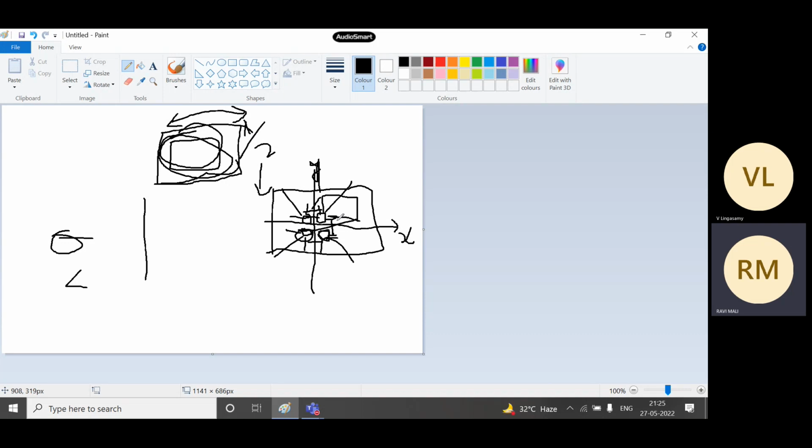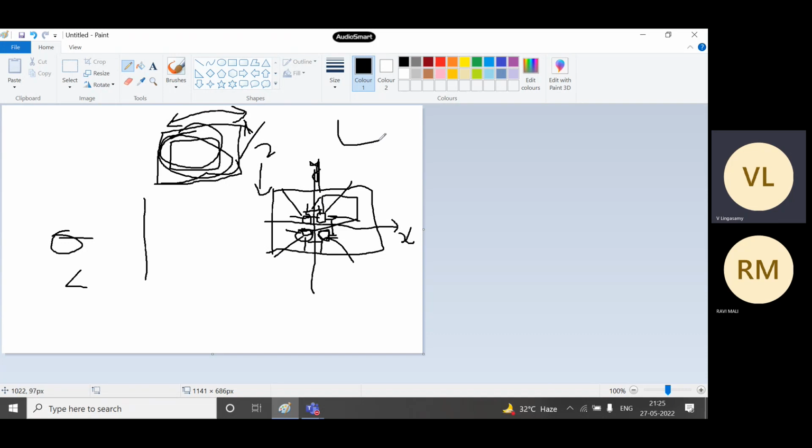You have to separate the first quadrant, and then place the elements. In the parameters you define in CST, you can create a variable called spacing_x and another called spacing_y.